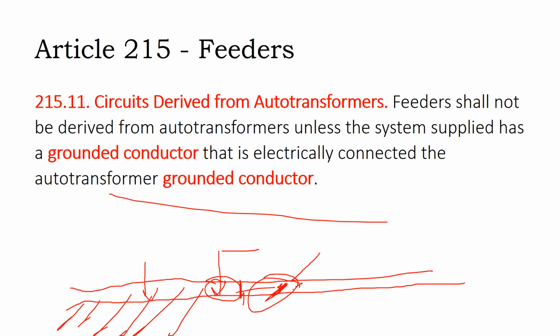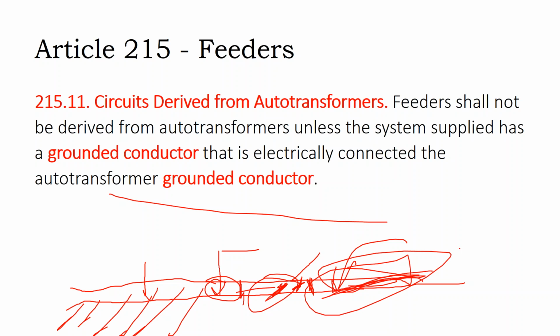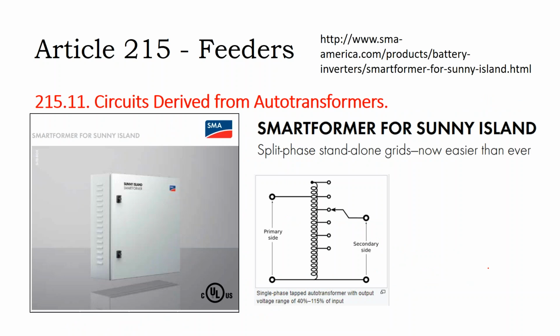Furthermore, this mud sediment layer is so thick that it doesn't get very good resistance either. Eventually what you have to do is hollow out whatever ground you can and lay that ground rod flat in the ground and bury it. Well, it still might not give you the resistance you need, so you might have to install multiple ground rods up to the point where you get the resistance that you need. You might be called in the National Electric Code to install additional ground rods. So we'll get to that when we get to that section.